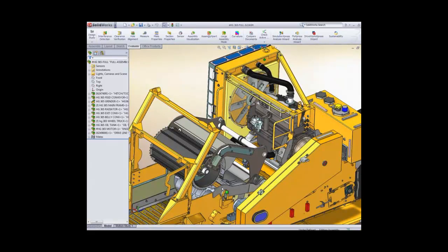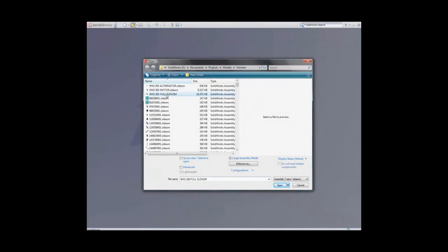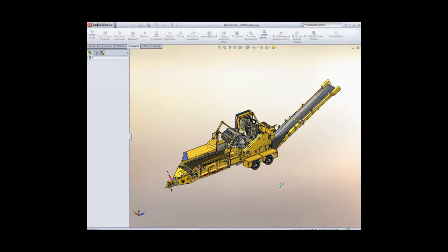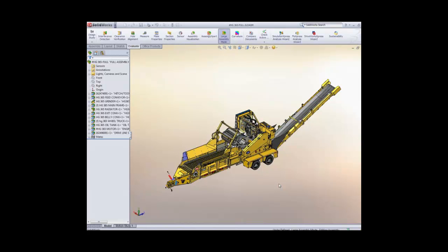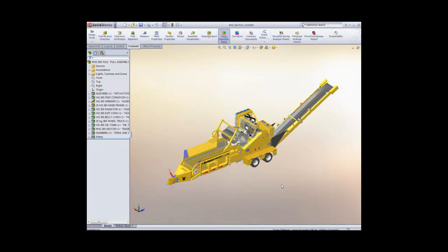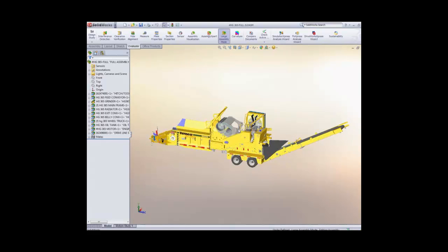So how can you share your complete designs with colleagues, customers, and suppliers who don't have the latest hardware? What do you need to do to get Solidworks to open this assembly on a less powerful machine? Well, the answer is absolutely nothing. Solidworks detects the number of components in the assembly and activates large assembly mode. This opens all the components lightweight and switches off the nice looking graphics like reflections and shadows. Now the exact same assembly opens in around 20 seconds with about 1/10 of the memory used, and the level of detail is reduced when rotating to make it fast and interactive.